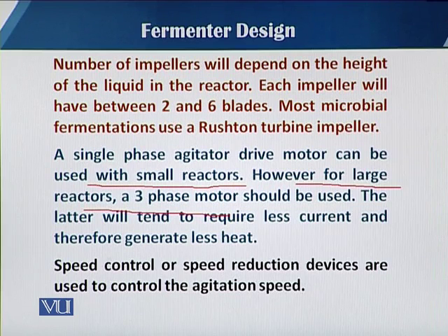If the motor produces heat, that can affect the temperature of the fermentation vessel. So we have to keep in mind the type of the motor and the capacity of the motor. That is very critical, because a high power motor has more power consumption, which can increase our process cost.